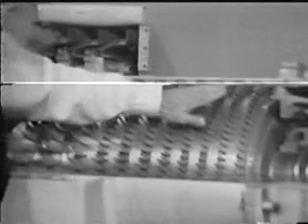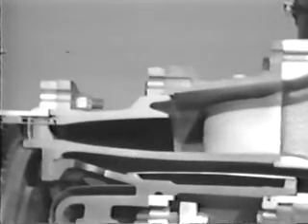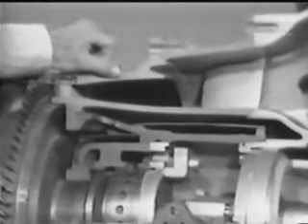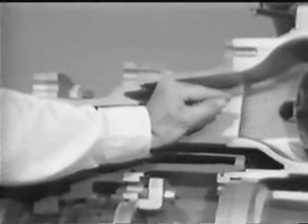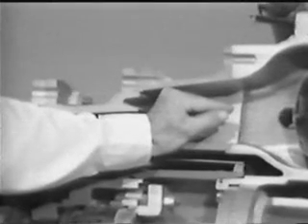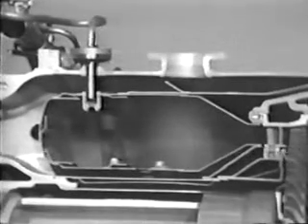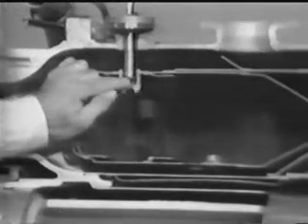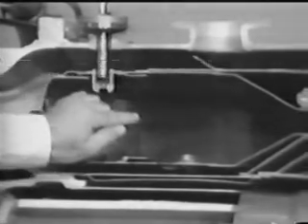After the air leaves the compressor, it enters the diffuser area. In the diffuser, an additional pressure rise occurs. The pressure at the exit of the diffuser is about 118 pounds per square inch at operational speed and full load, right about here. After the air leaves the diffuser, it enters the combustion chamber, where either liquid or gas fuel is added to the air.